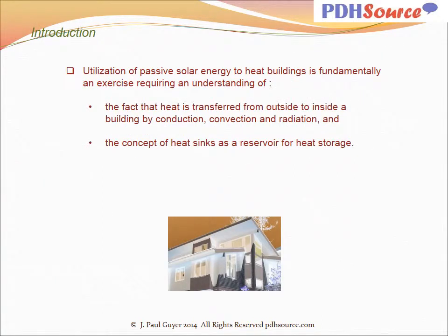Utilization of passive solar energy to heat buildings is fundamentally an exercise requiring an understanding of, first, the fact that heat is transferred from outside to inside a building, or vice versa, by conduction, convection, and radiation, and secondly, the concept of heat sinks as a reservoir for heat storage.